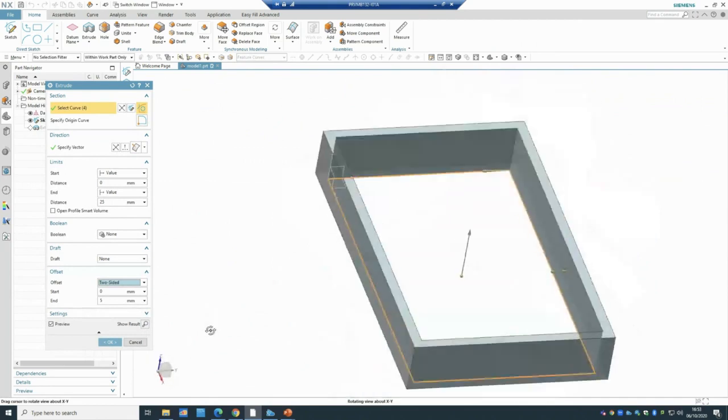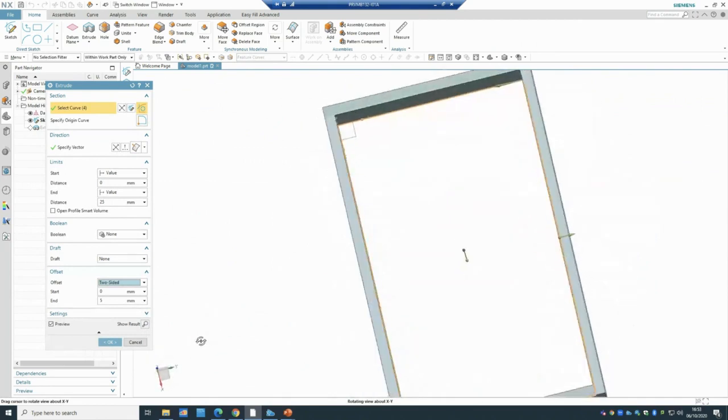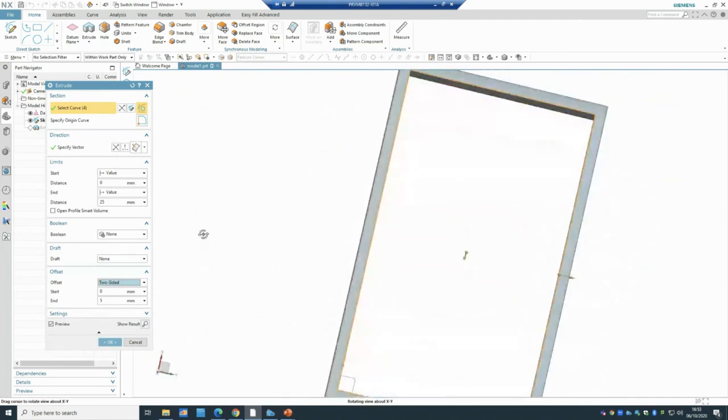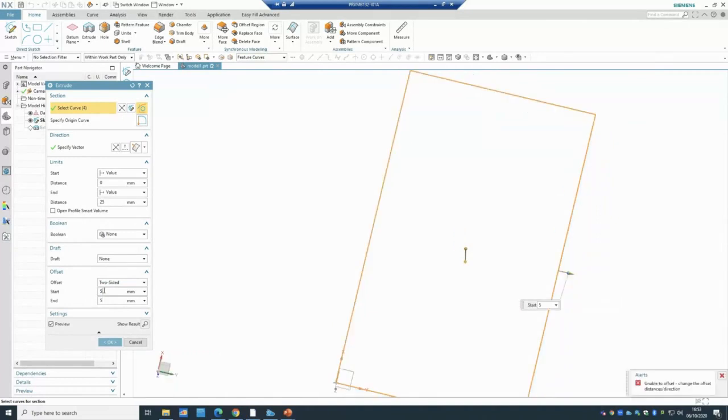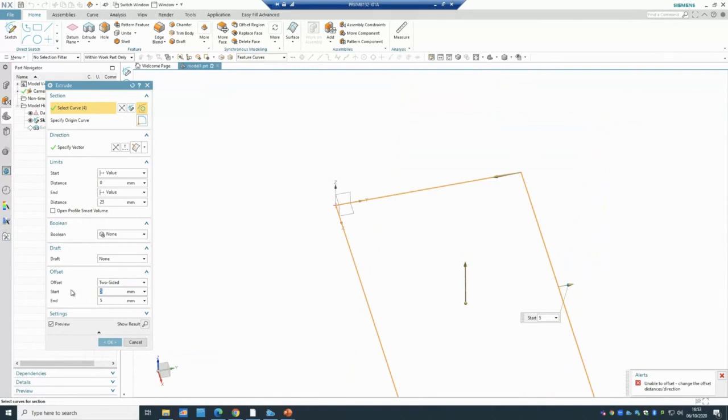So what's going on in here, I'm using the two-side offset with a distance of 5 mil. So 5 mil from that direction, I will add 5 mil to the other direction, see what happened. So let the software run it. Oh yeah, because this one is closed. Because I have the closed loop, it doesn't let me do it.